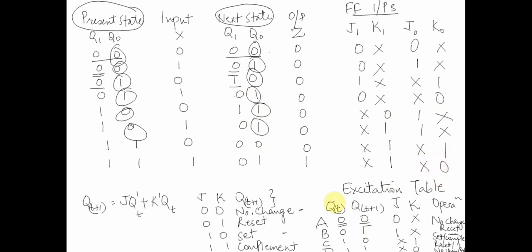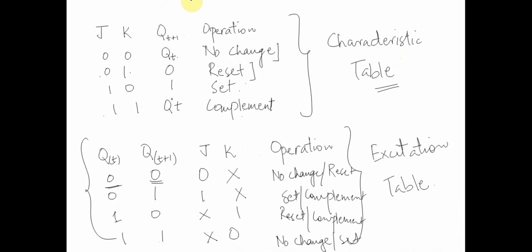Now we have completed our flip-flop inputs, and we can simply get the equations at the flip-flop inputs J1, K1, J0 and K0 using a K-map as a function of present state and input. So basically, if I have to copy it again to the next, let's come here. Now design example continued.